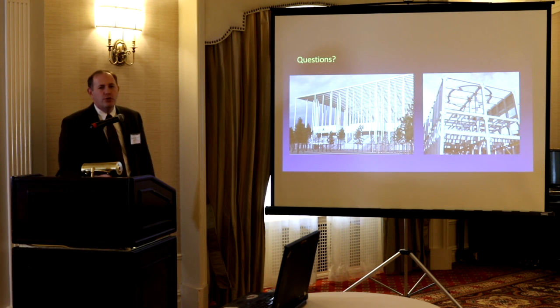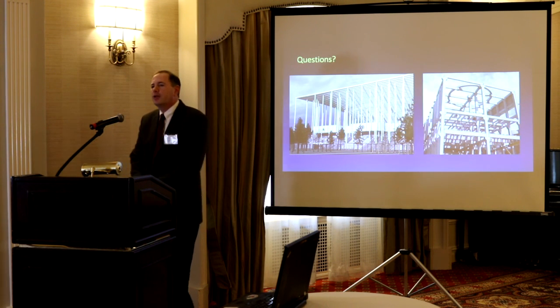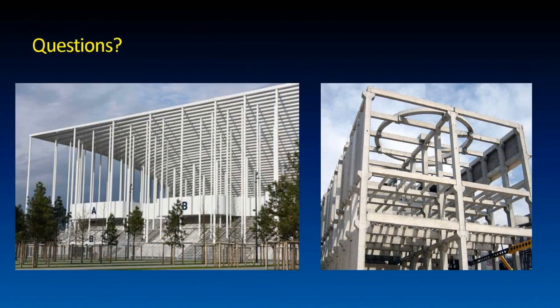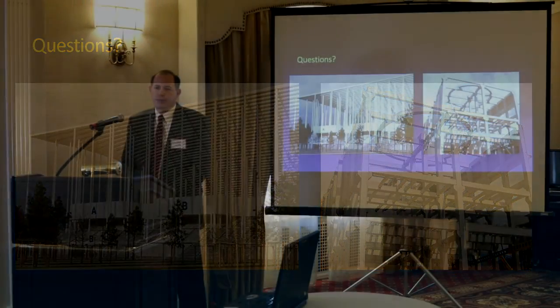So you can see they're using slender columns in the precast pre-stressed world quite a bit too. For PCI, we have also gotten some guidance to them. The 0.4 EI works really well too. So you can use the 0.4 EIs. We have the equations also. Those will work for the precast.